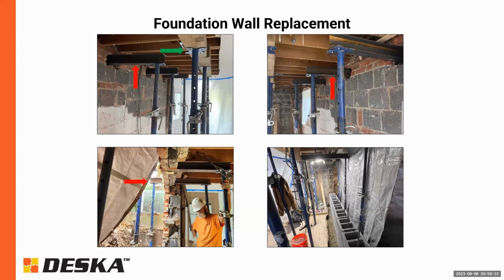So the construction of this home has a brick facade as well as a 4-inch thick brick exterior wall, both of which are very, very heavy. And by just supporting the floor joists above or the floor above, you're not going to be supporting that very heavy exterior wall. So these beams had to be designed and installed.